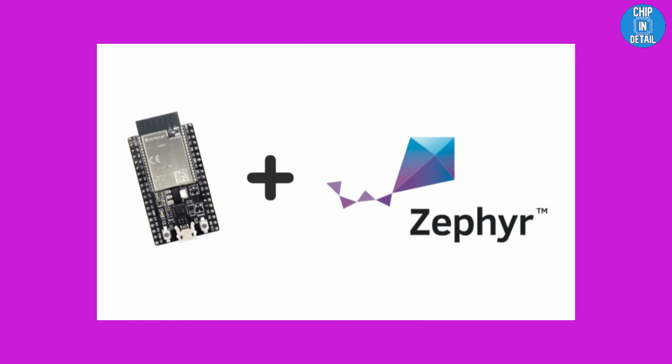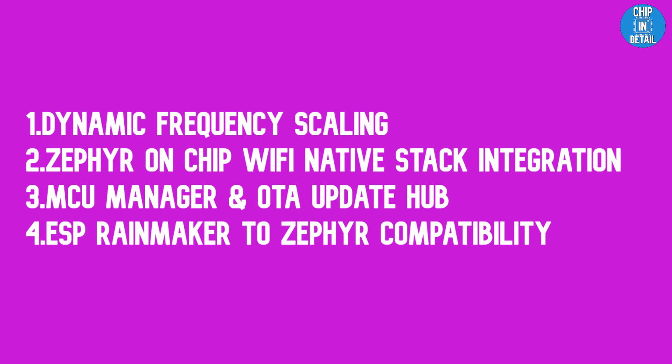As of now, Zephyr RTOS only supports ESP32 and development work is going on for ESP32 S2, S3 and C3. Currently, Zephyr RTOS is working on a few features for ESP32 like the following. Dynamic frequency scaling that can save a lot of energy, Zephyr on-chip Wi-Fi native stack integration, MCU manager and OTA update hub, ESP Rainmaker to Zephyr compatibility.